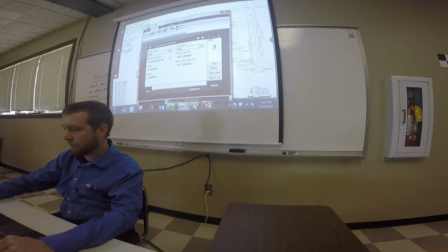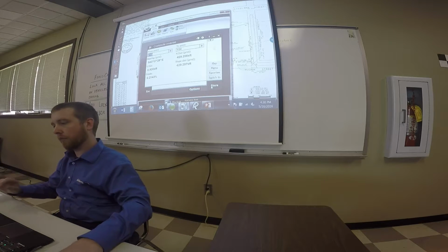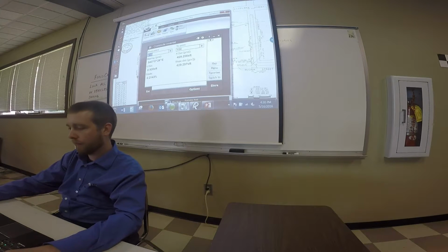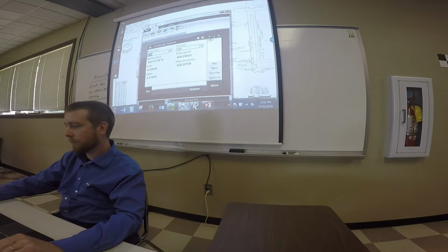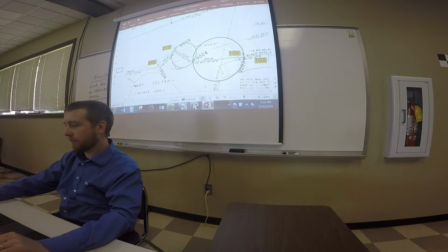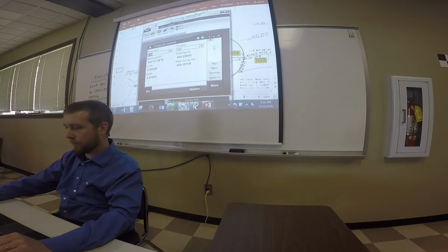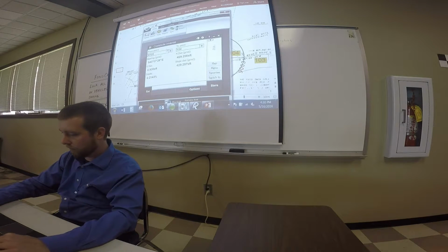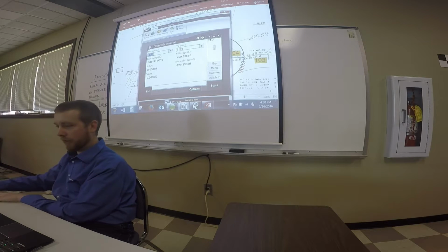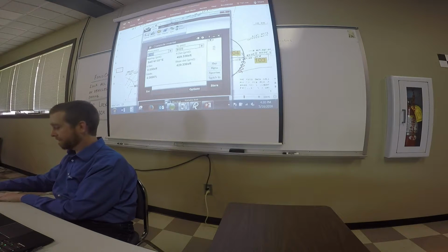210 and 104. All right, so it's telling me it's 429.3 feet. Then I'm going to inverse what the original surveyor said it was, which is going to be your 9,000 numbers. So 9105 and 9103. What's that inverse? 429.3. It's about 4/100ths longer. All right, so that just gave me a tremendous amount of confidence in the position of the two pins I found.